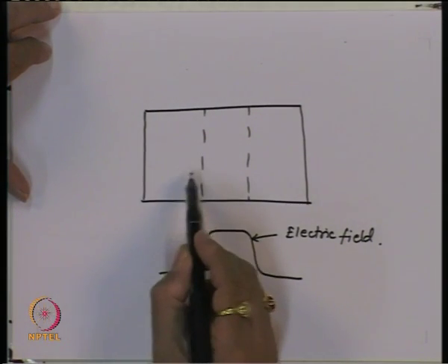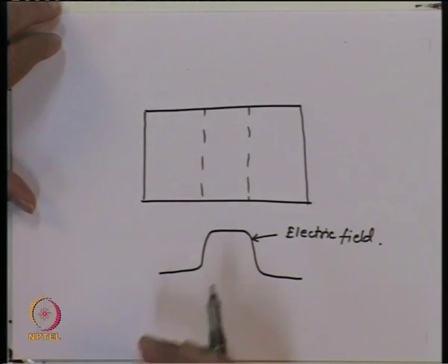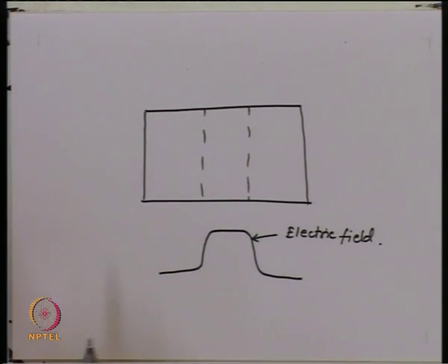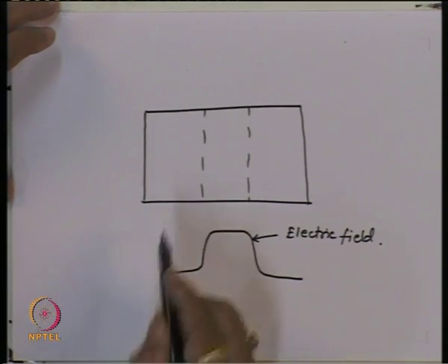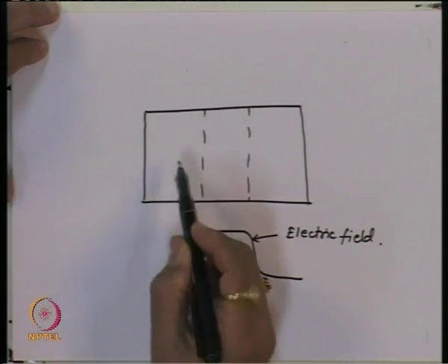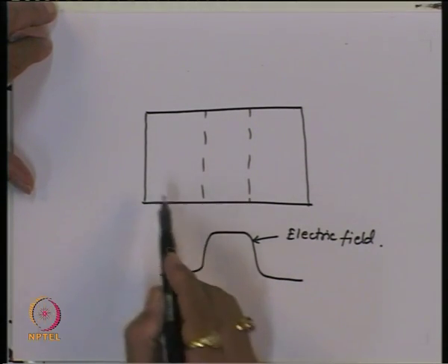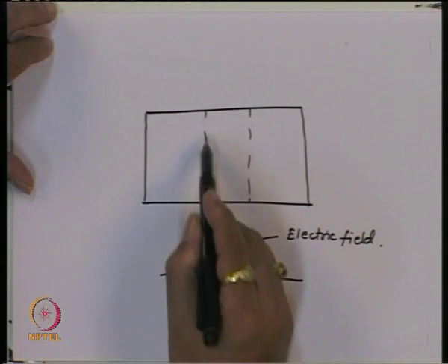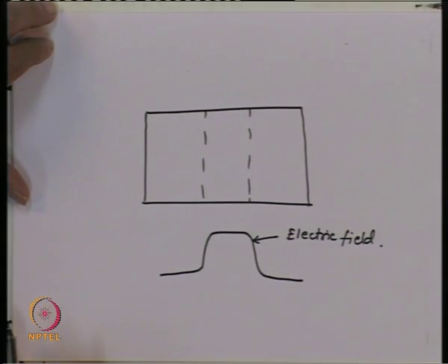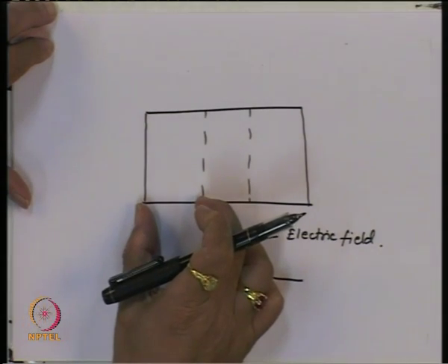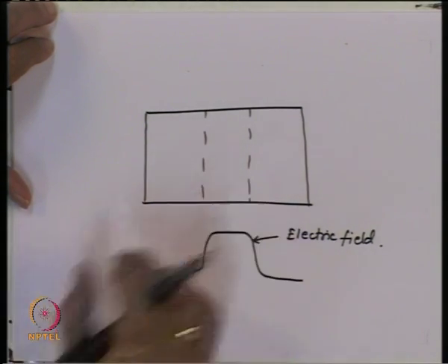Now, since the diffusion process is a slow process, if we want the current to respond as quickly as possible to the photon flux, essentially this diffusion process should be minimized. What that means is that most of the photons now should get absorbed inside the depletion region. So, the first thing that should happen is that this region should be as small as possible.